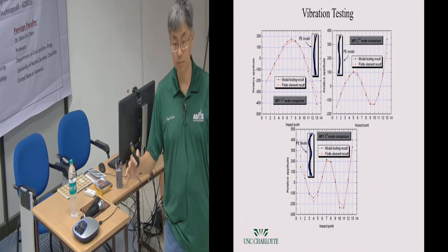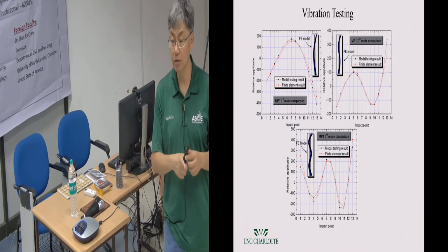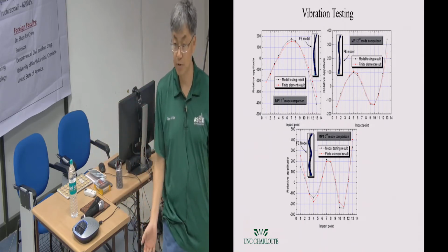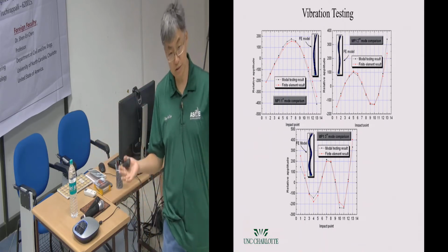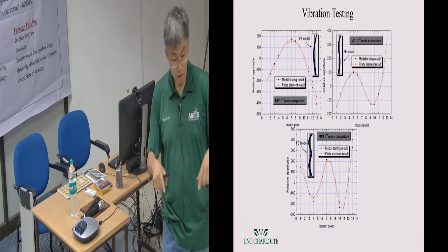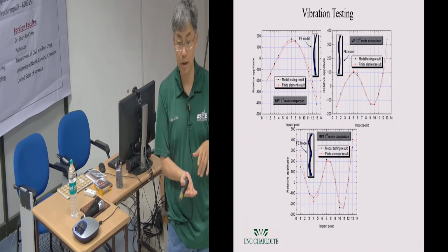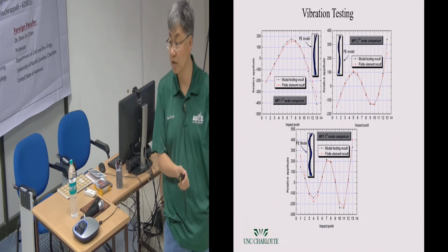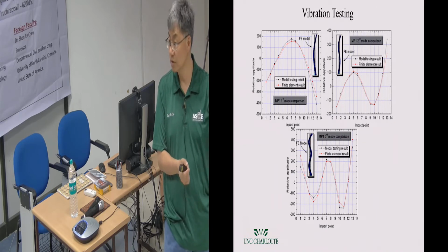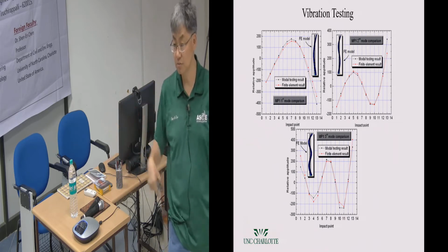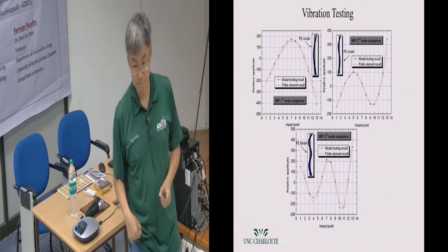is the problem, and the only way you can tell that is to do, for example, this slab has a vibration problem. How do you know whether it's a boundary connection problem, or if the slab doesn't have strong enough stiffness? Or maybe somewhere you have weak, poor concrete sections. You have to do a full-scale model testing of this facility.